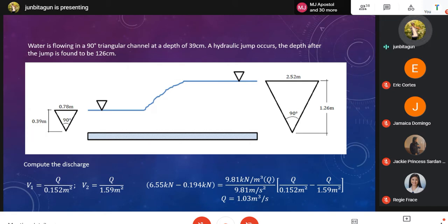So, what are our equations? We have no head loss here. Why? It is not a closed pipe. But there could be friction here, guys. But without considering the friction or head loss, we have the velocity, v squared over 2g. We have no pressure since it is open to the atmosphere. Then we have z. So only two. It would be the energy due to kinetic, v squared over 2g, and the energy due to potential, which is z. That is the only energy we have here.